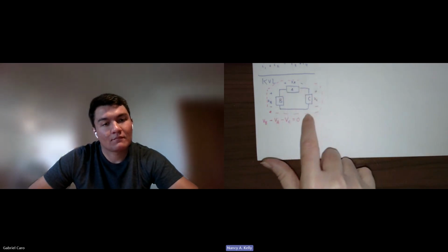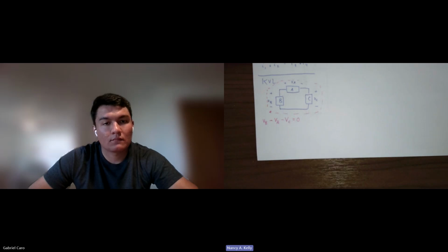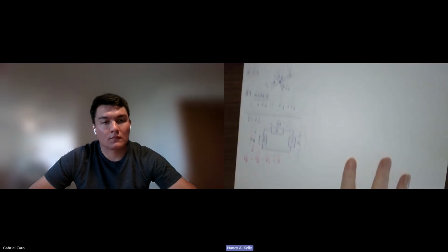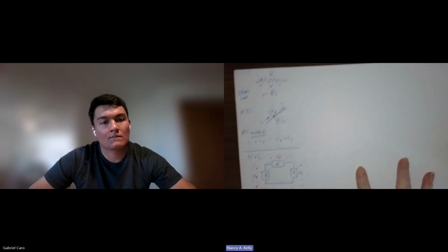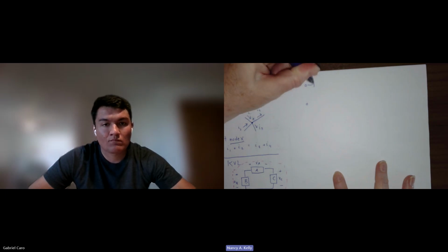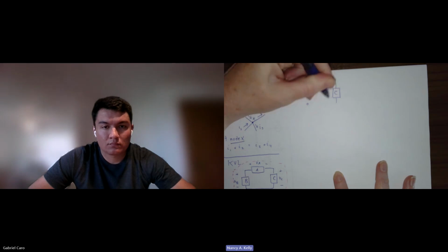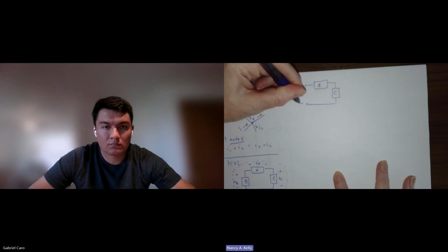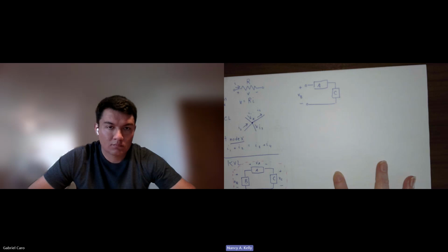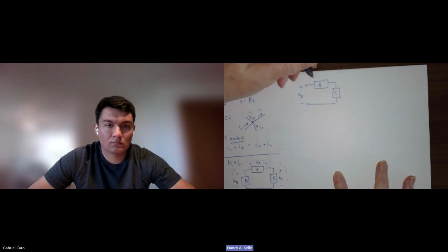Now, in this particular case, the path that I chose, everything's connected with a wire, but they don't have to be. As long as I know the voltages between 2 points, that's good enough. So, for example, I could do something like this, where let's just say I have an open here, and then I have A, and I have C here, like this, and I happen to know that the voltage between these 2 points, which I can measure, is VB. Even though there's no element there, there's no wire there, this is still VA, and this is VC.